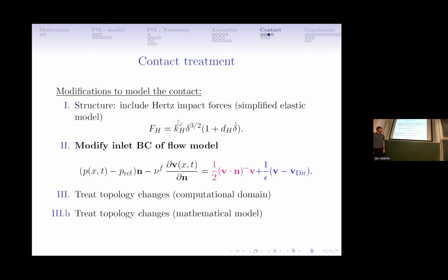Okay. This is not so difficult, but more difficult is to also address the fluid flow problem, where there is a huge increase of the pressure once the channel is closing. As I introduced before, we can describe this behavior quite well, with reasonable work, by the penalization boundary condition, where we choose a sufficiently small penalization parameter.